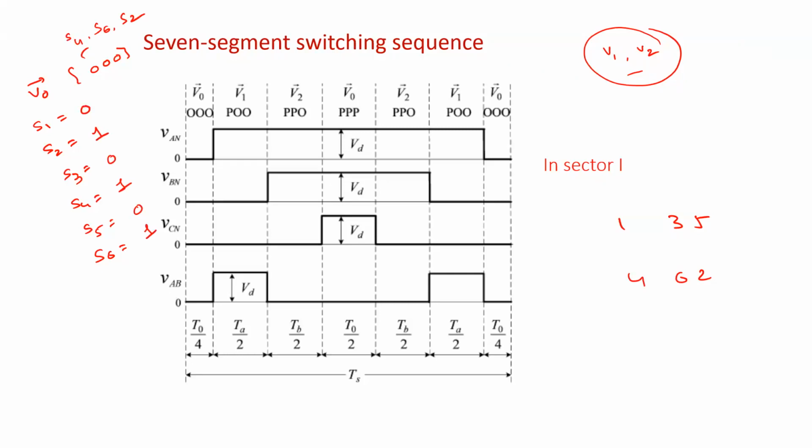You may confuse it, right? How to implement V0 vector or V1 vector or V2 vector. So this is like this you need to select, or like this we need to program this. And you have to make sure that we have some timer, so that stops at T04 time. Once that sample time T04 is elapsed, we'll start with V1.